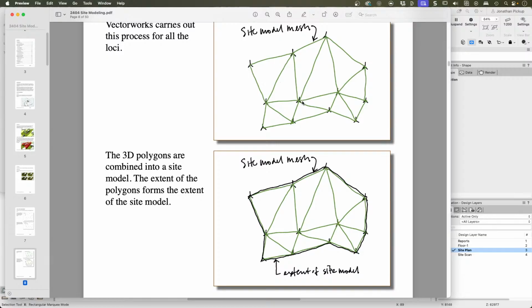And then if this one was, for example, if that was 10 feet and that was 30 feet, well then halfway along it is going to be 20 feet. And so between that, that's where 15 feet is. So you'll end up with a contour that goes from there to there and then comes to here. And so sometimes you end up with these very funny shaped contours, and it's really a result of how Vectorworks works through the mathematics of all these objects.